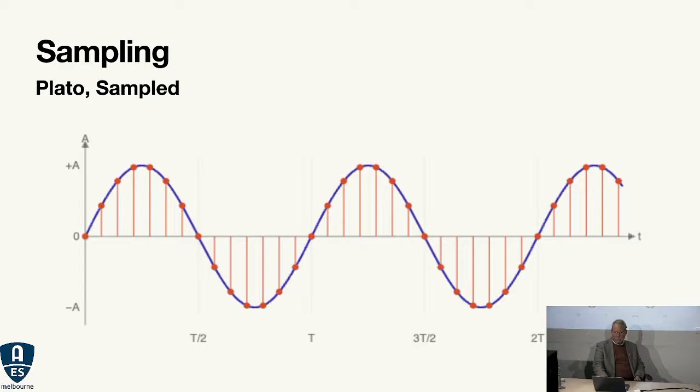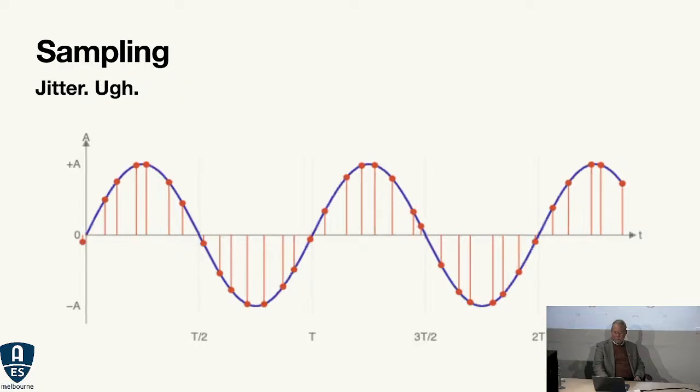But dark clouds over the horizon. Jitter. So jitter is moving the sample points back and forth randomly. And this is truly random jitter. This little plot here is approximately 30% jitter, which if you pretend this is a 48 kilohertz sampling, that's about 2 microseconds of RMS jitter, which will become clear what that number means in a little while, hopefully, if I do okay.